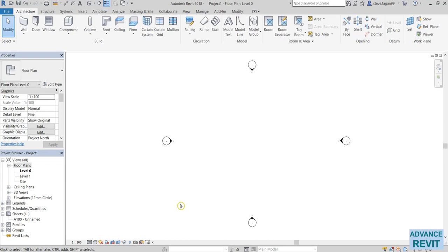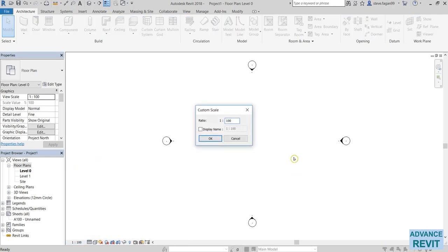Again, if you're familiar with AutoCAD, in your model space you'll have a scale of 1:1, and then in your paper space, that's where you'll create your viewports and then scale on your sheet. So with Revit, what you do is you apply all of your visualizations and scalings, etc., to that specific view. So it's currently set to 1:100. If you select it, you'll see our typical list of scales. If what you want isn't there, just selecting custom, we can create a new scale.